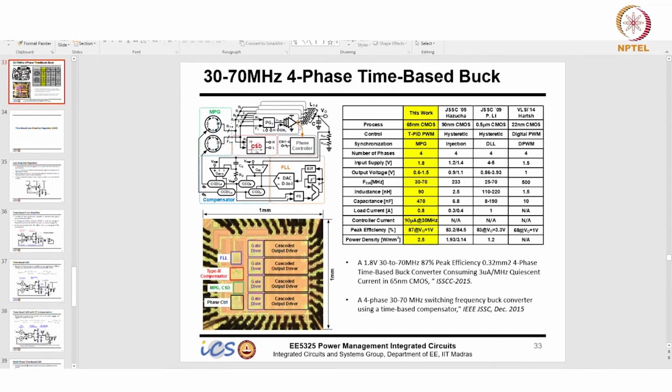But the VCO is running at 4x, so it will have some extra current obviously. But if you compare this extra current from running the VCO at 4x with the complexity and the current you require to generate for the current balancing and all those, that is much simpler here. Because current sense itself is not a simple